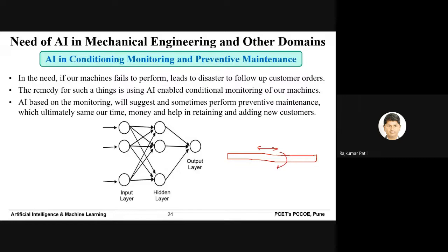So in order to restrict the axial movement, magnets are placed in the axial direction, whose role is to avoid the axial movement of the shaft. Again, in order to restrict the radial movement, magnetic bearings are placed in the radial direction. They will make sure that there is no significant movement in the radial direction as well.